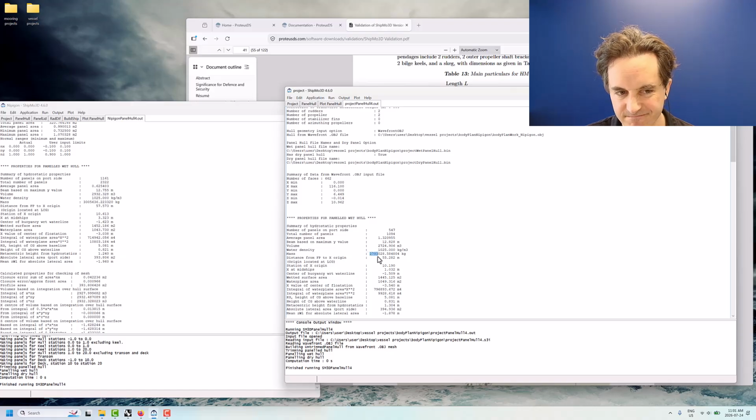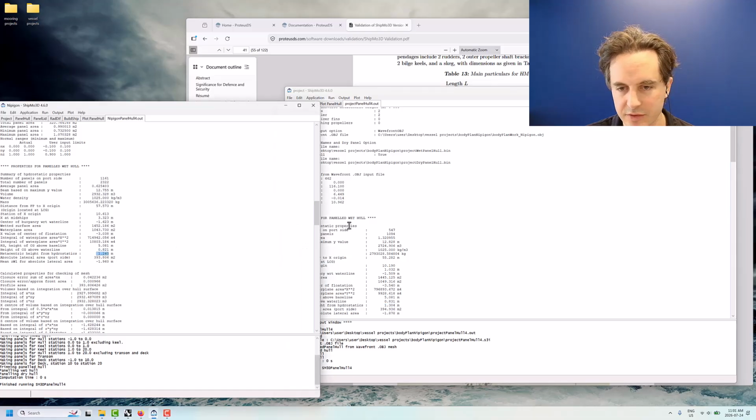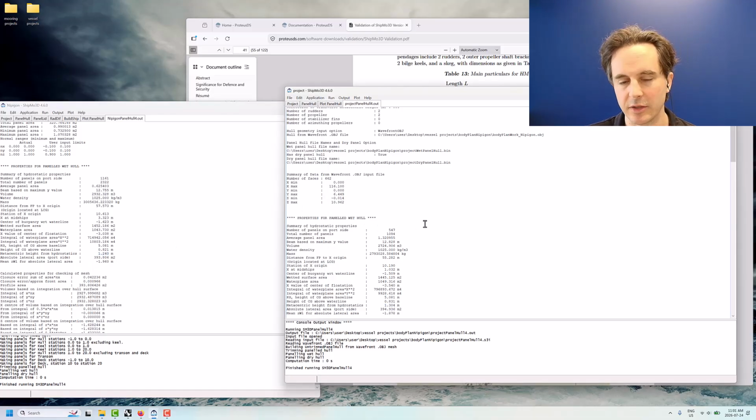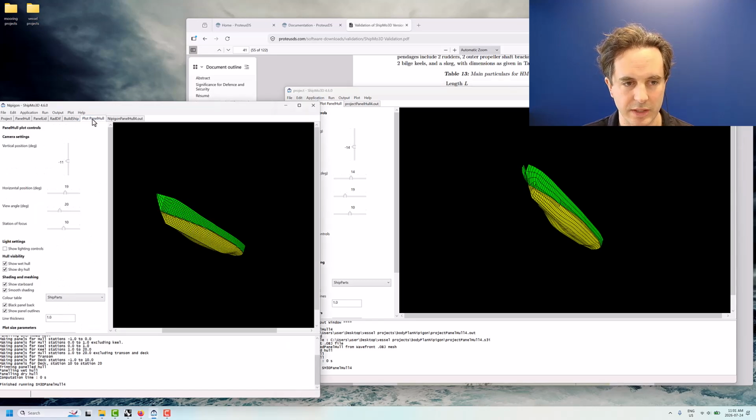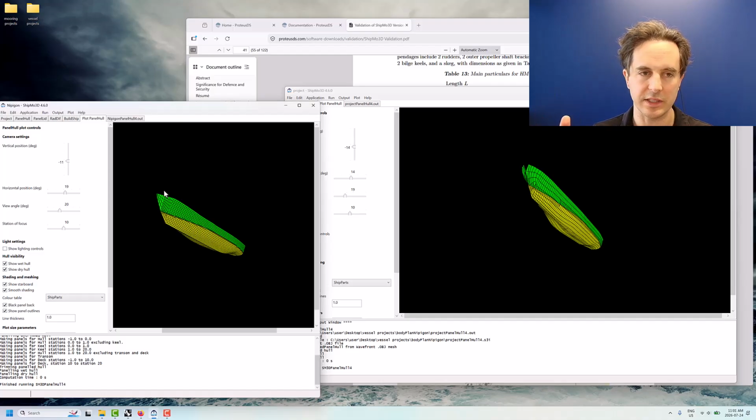It's a little bit lower. Metacentric height 1.3 meters, 1.24 meters. So obviously as we added more detail in the hull lines, we'd get a lot closer to it and maybe work a little bit on fairing it, smoothing out the hull. It would look good. But generally what I wanted to do is just show that idea of how to go from this rough 2D drawing to getting a hull and having some confidence that this is going to work. So that's all for now. Thanks for watching.